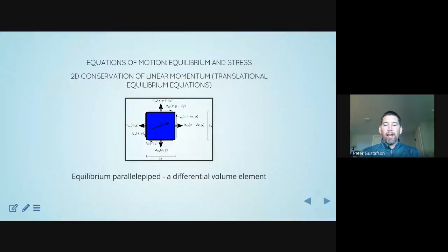Now, the caveat to that is the caveat that I just gave, that when you have repeated principal values, then you lose the uniqueness of the 3 principal orientations. What that means is that within a plane, all the orientations within that plane are equally valid principal orientations, or by that argument, equally invalid principal orientations. They're arbitrary in that plane.